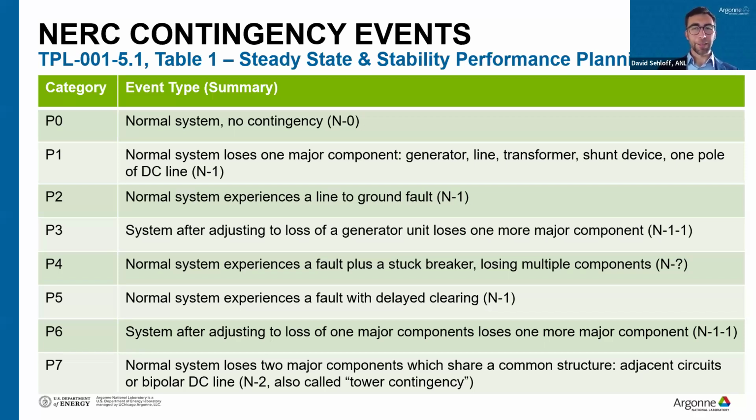The number of contingencies, if we're looking at joint contingencies happening two at once or more than two, the combinatorics means that the number of contingencies we need to study grows hugely, very quickly. So this kind of puts some bounds on what contingencies need to be analyzed, and the planner has some freedom to define what are credible contingencies, which ones we need to consider, which ones we can neglect in our planning.